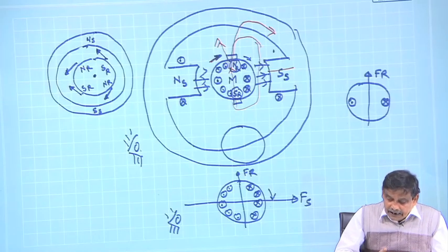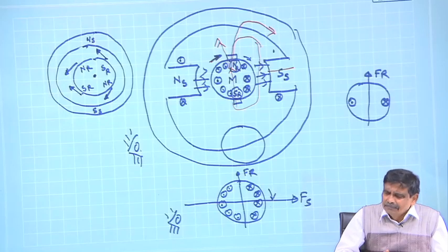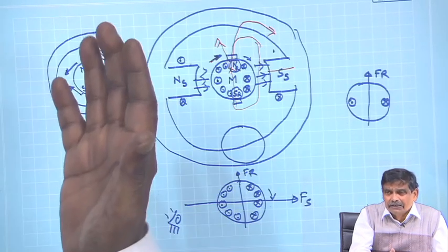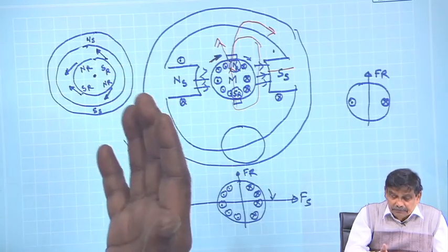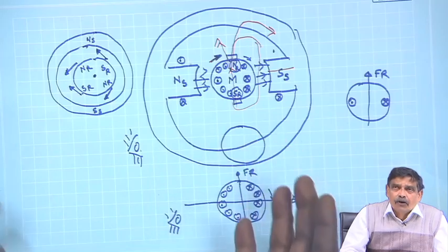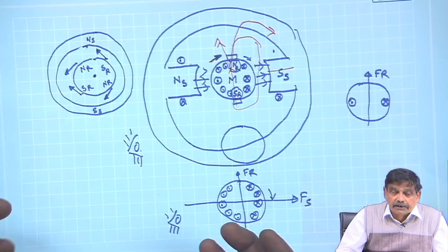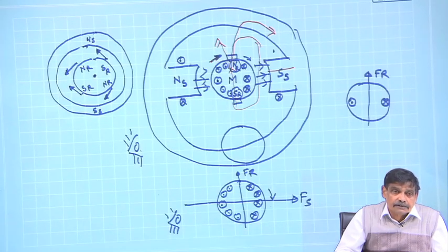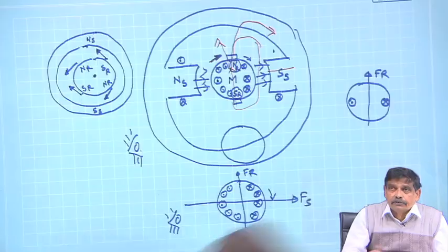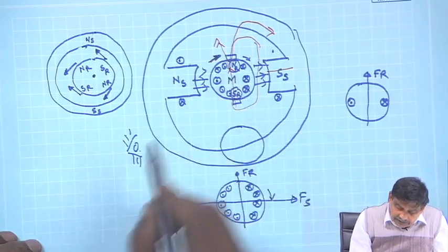But the important point is that when I say the field is rotating, you should not be bothered about whether this stator is stator or whether that rotor is stationary or not. Either way it can be done. The rotor may remain stationary, it carries 3 phase balanced current, and it is observed that it produces a rotating field. Here two things I told.